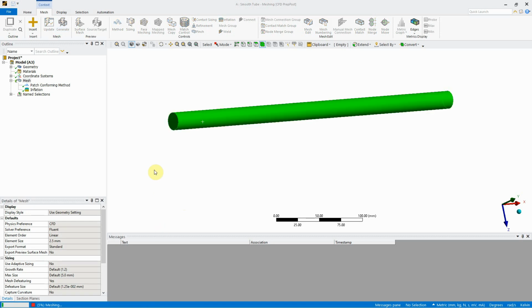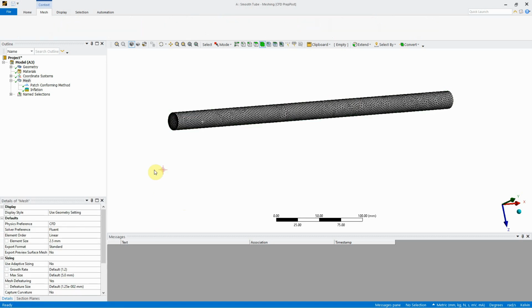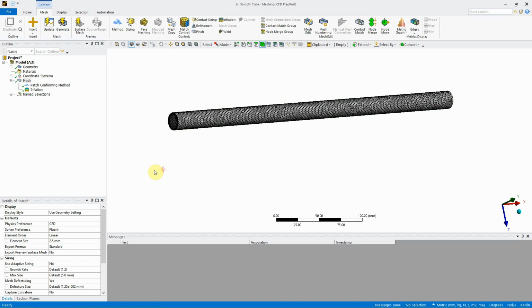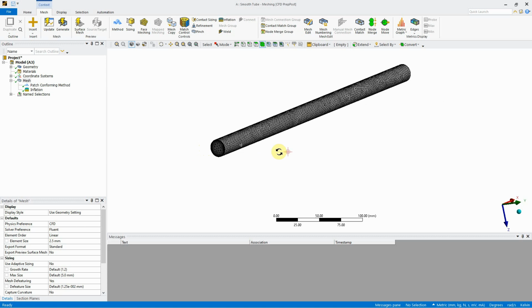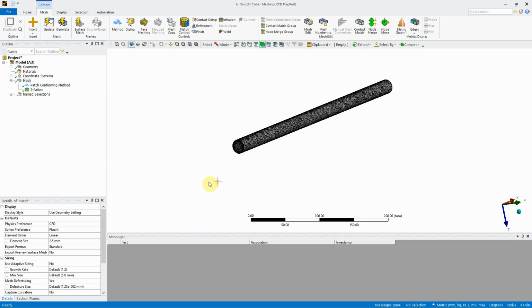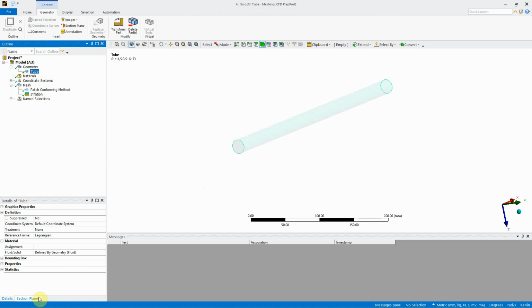Now you can do a mesh dependency study, but depending on the amount of effort that's needed on this, I would be very skeptical, because if you're using a student version license, you will be limited to the number of elements. If you're here on campus, I guess you can do a mesh dependency, but it's not a requirement, and I would refrain from going down that path. But this mesh here is quite adequate to do this analysis. Student and full version.